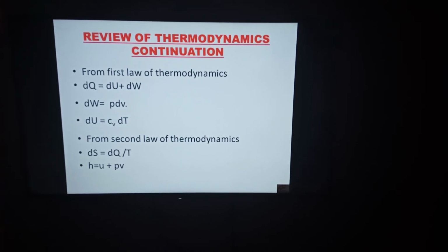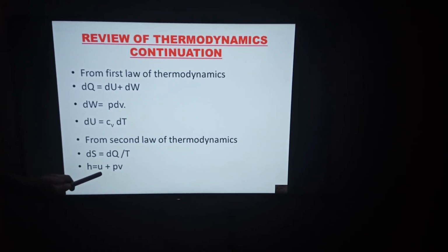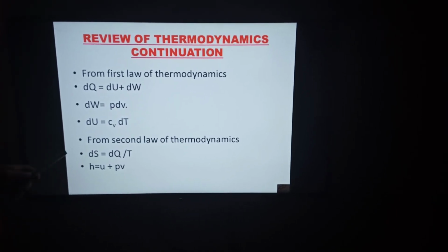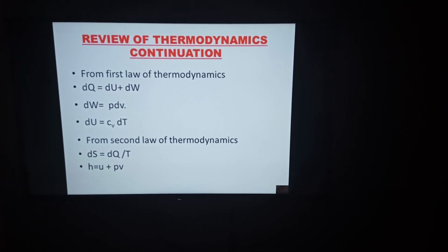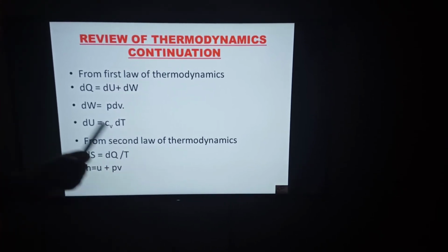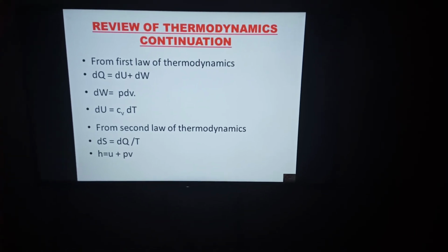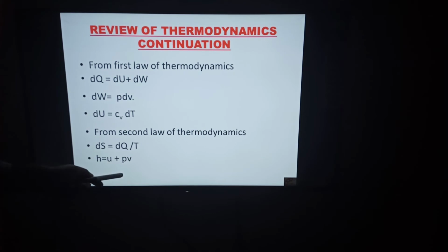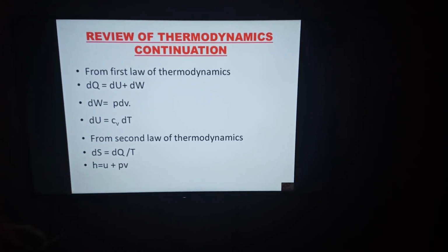Enthalpy plays the same significance as that of internal energy in a closed system. That is, in an open system, enthalpy plays the same role as that performed by internal energy in a closed system. So in other words, we can say that enthalpy is nothing but internal energy plus pressure volume energy. This is known as flow energy.